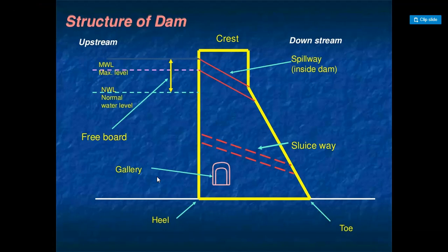They serve to drain water seeping from the dam body, provide windows for dam checking, provide a space for movement and for grouting contraction joints, and provide enough space for carrying pipes during artificial cooling. So, freeboard. It is the part of the dam structure between the top of the dam and the highest storage level.